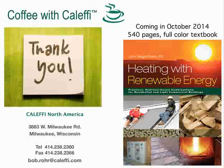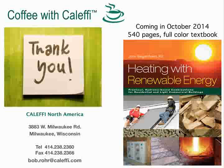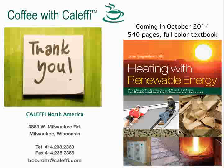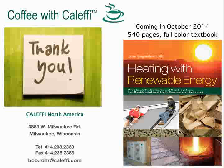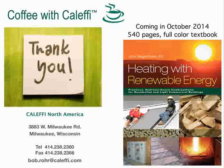Yeah, definitely. And most of them are usually on the balance of the system. Hopefully most people, if they're doing geothermal heat pumps now, are perhaps IGSPA certified or have been trained or assisted in designing the earth loop. But I'll give you a good example of a common error, which is putting in some type of radiant panel system that is not capable of operating at those low water temperatures. Stapling the tube to the bottom of the subfloor without plates, stapling the tube to the side of the floor joists, is a bad idea with any kind of heat source.